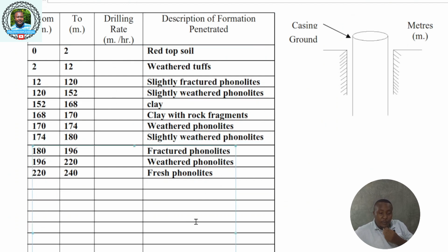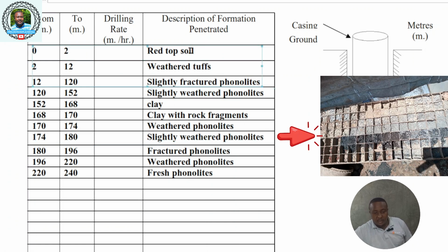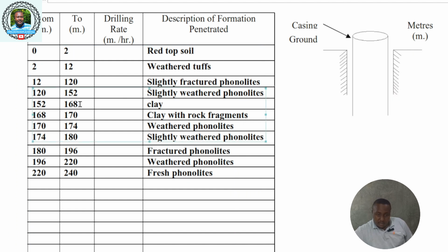Now, as I told you in episode 2, there is something called a sample rack or a sample box. This is where the soil is recorded in intervals. So you see from 0 to 2 meters, they recorded dry topsoil. These are the logs of the specific borehole, and they do vary from area to area. This was in Nairobi; if you are drilling in a different area, this is how they got the logs. So read them like that.